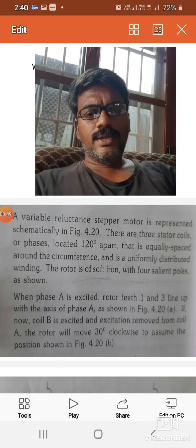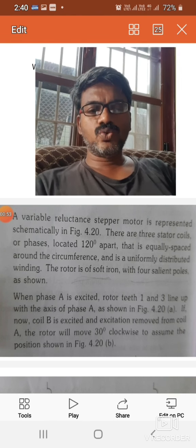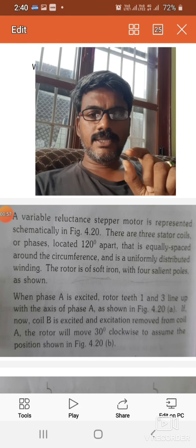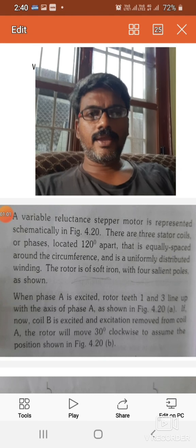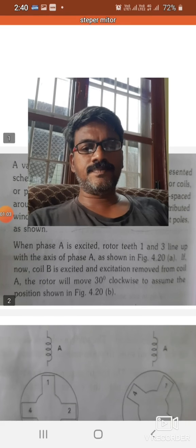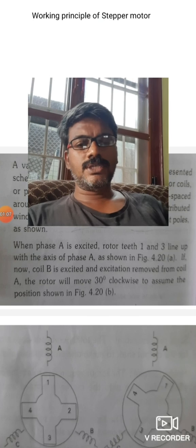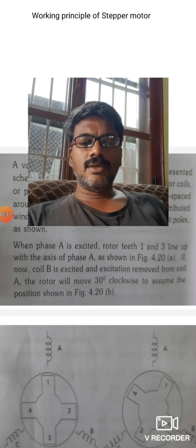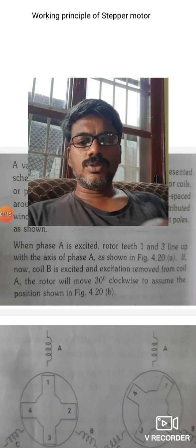Again, it is a very important point to note that the control has two elements. The number of pulses which determine the angle of rotation, and the direction of data which determines the order in which the poles are excited. The two controls are there.